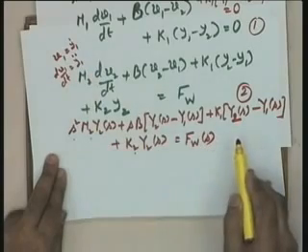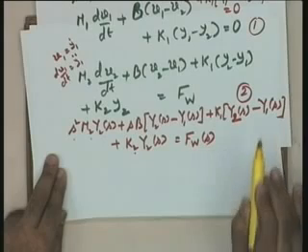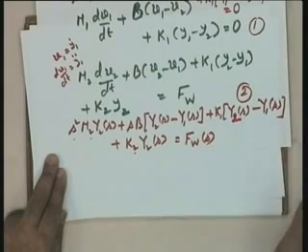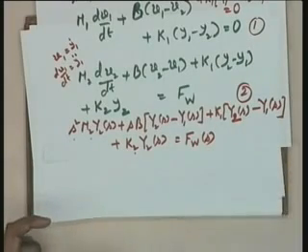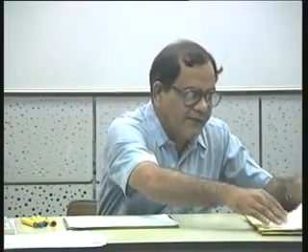So, now you will see in this particular case there are three variables y1(s), y2(s) and fw(s). You are interested in y1(s) and fw(s). So, you have two equations, you eliminate y2(s) and this gives you the transfer function model, which I have written for you and I leave it for you to verify.